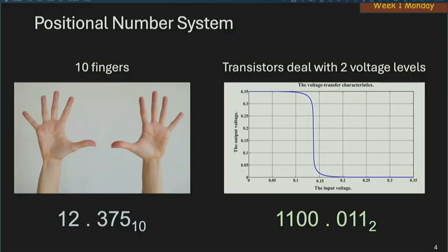If you have a sequence of inverters, if they have linear reaction, then suddenly this error will propagate and they will increase. But with this kind of behavior, there's a saturation region, there's a cutoff region, then you get reliable computation with dozens of inverters back-to-back, and eventually billions of transistors back-to-back.